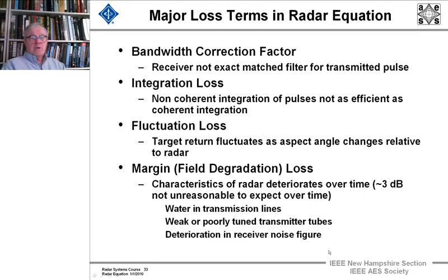But when you're really putting a radar together, every different group of people building the different subsystems has to have an allocation of losses which they believe they'll get, and they have to be held to their losses. Because you can see there are 8 or 10 different subsystems, and then the atmosphere and the target, and if each one of them loses a half a dB, your detection range will drop a huge amount.